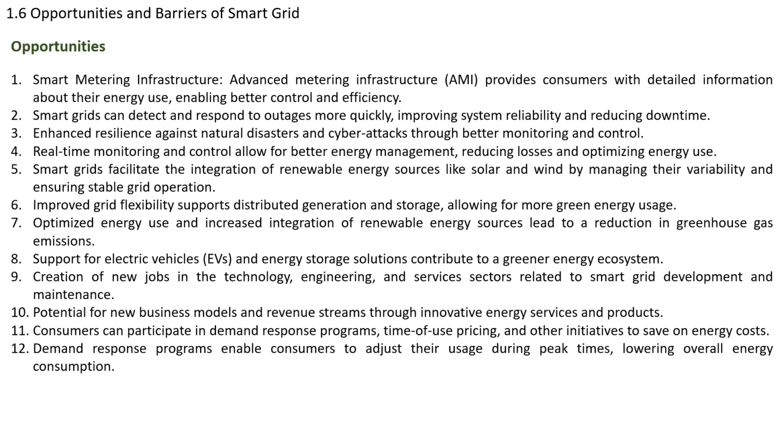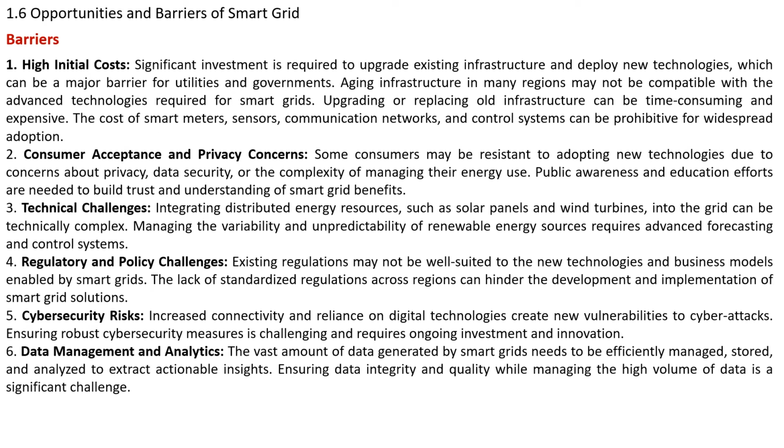There are also new business models and revenue systems, and innovative energy services and products come into the picture. Another main opportunity of the smart grid is that consumers can participate in demand response programs, like time of use pricing, real-time pricing, and other initiatives too. We can save on bills or energy costs for consumers. Demand response programs enable consumers to adjust their usage during peak times, lowering overall energy consumption. These are the opportunities of the smart grid.